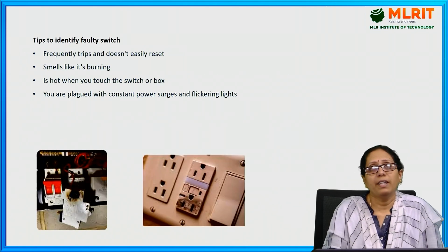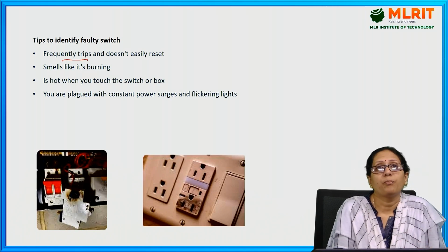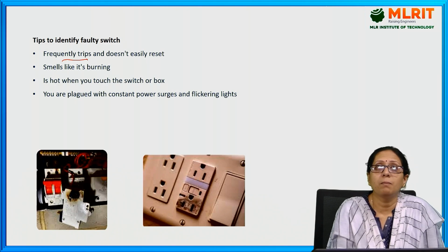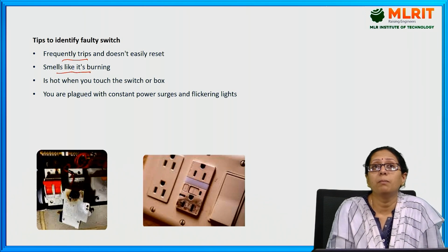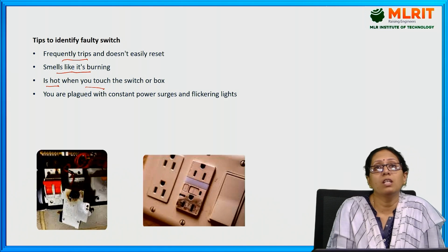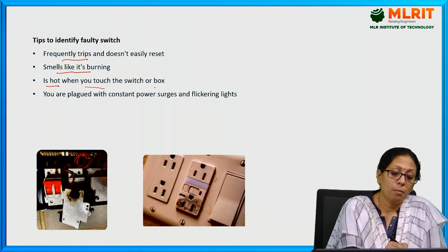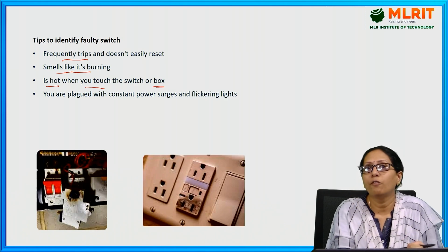Tips to identify a faulty switch. What are the tips? Frequent tripping of the MCBs is one indication of a faulty switch, and a burning smell also indicates that some sort of fault is there in the switch. If the switch or the box is hot when you touch it, this is an indication that there is some kind of fault.